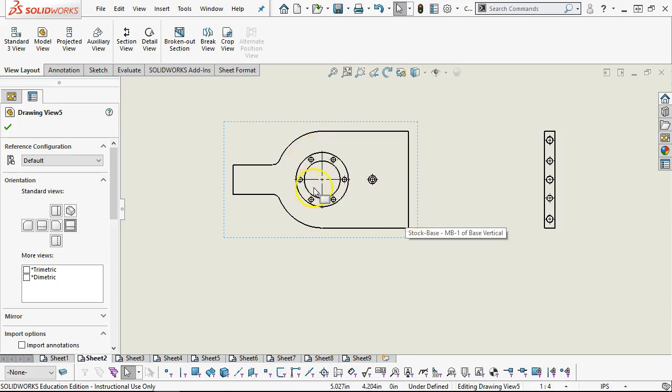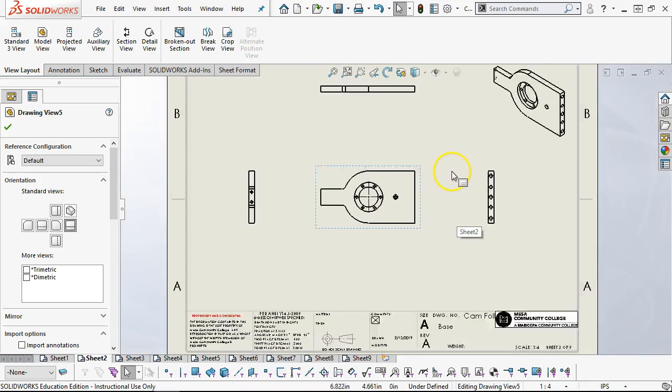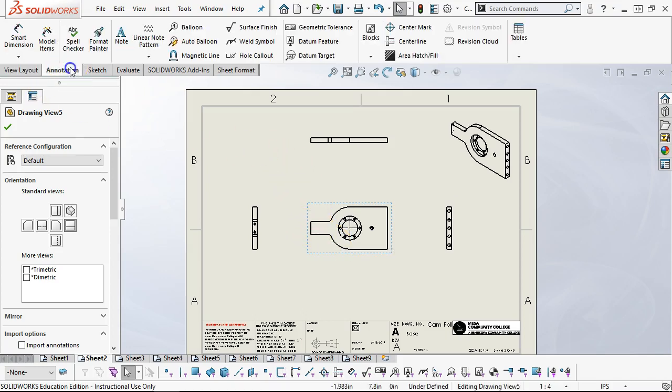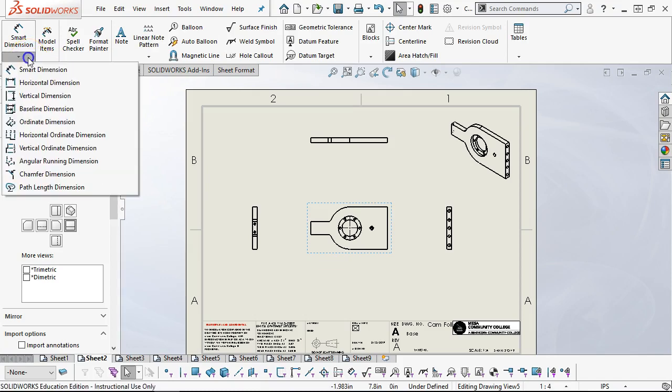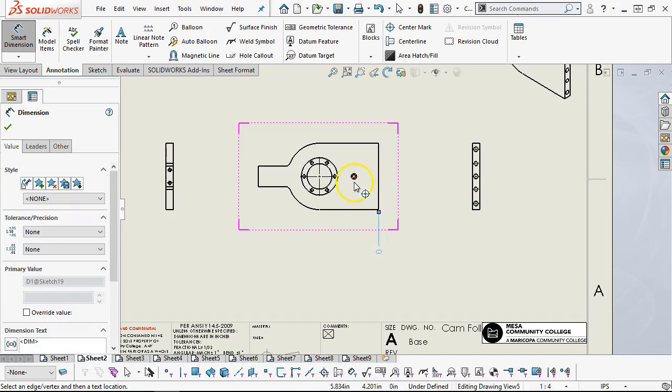And as we go through the process, the positional tolerances are the threaded holes, or these are the clearance holes on the plate side. All right, so basically what we just did on the base, you're going to do, going through adding dimensions. And expect that this is going to get a little busy. So the recommendation would be, instead of the baseline dimensioning, that you pick up the ordinate dimensions. And since we picked that as kind of our primary, then I can go through and pick up those dimensions.